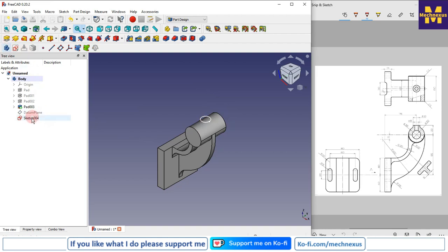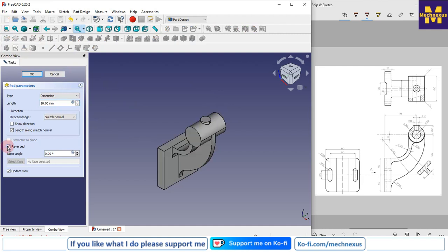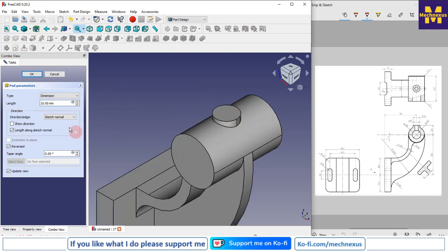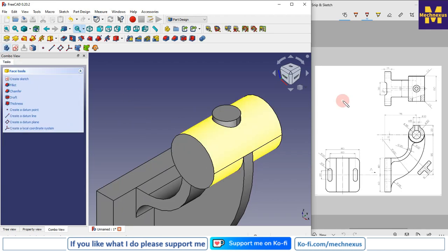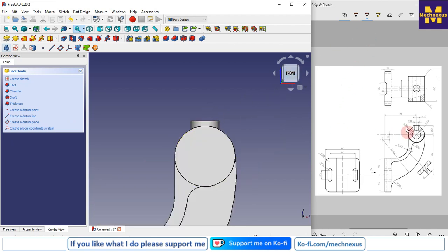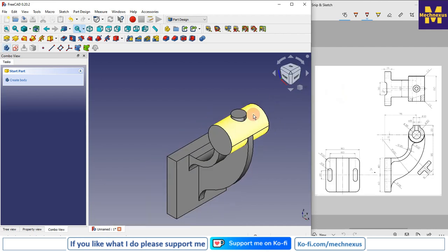Now I will click on my sketch and create a pad, and here in the condition I will select up to face and say OK. So you can see that a boss has been created similar to our drawing. Now we will do the material removal process. So we will start from the bottom and we will create these two slots.